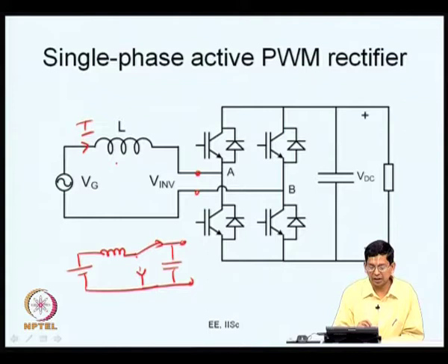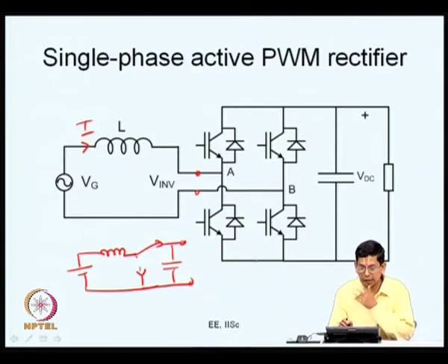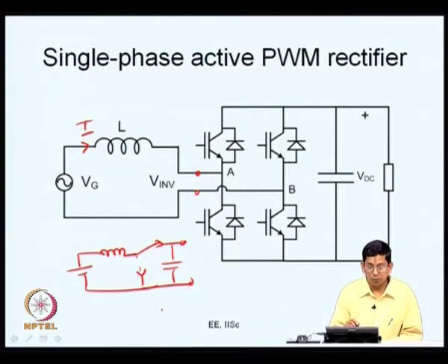You once again have an inductance now. You again have a single pole double throw switch here. At A is the pole, and there are two throws, and you have plus VDC here. The same observations can be made about the other one also. So, it is a boost converter. In a boost converter, what happens now? This is your pole voltage, and these are your throw voltages.